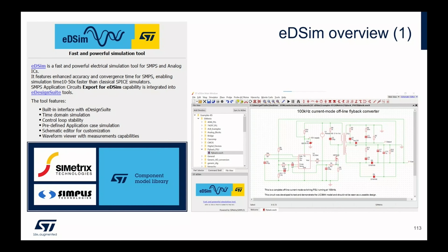In this case, we're going to be simulating a buck regulator, our new DCP3601, which is a 36 volt, 1 amp synchronous buck for industrial applications. And what is great about Simplis compared to PSpice is that Simplis was specifically designed to simulate very fast switching mode power supplies.